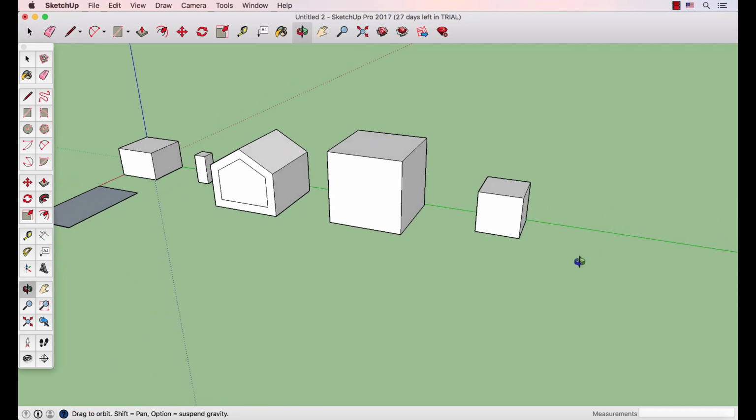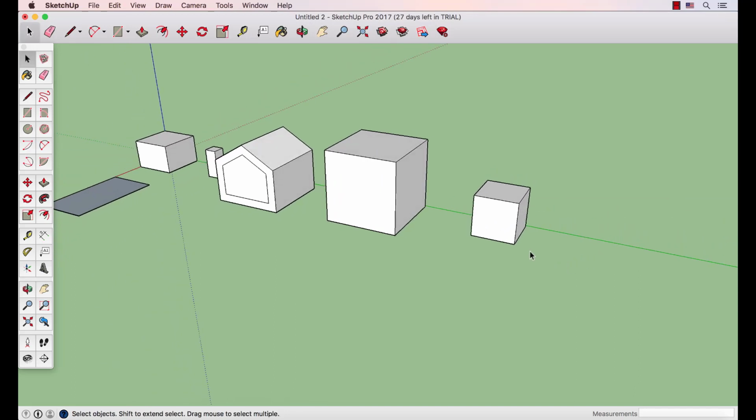To enable this tool, we can either press the spacebar on our keyboard or select this icon on the toolbar. When we open SketchUp, the Select tool is enabled by default. When our cursor has turned into the standard form, we can select an object. With one click, we select an entity that can be a surface or a line.